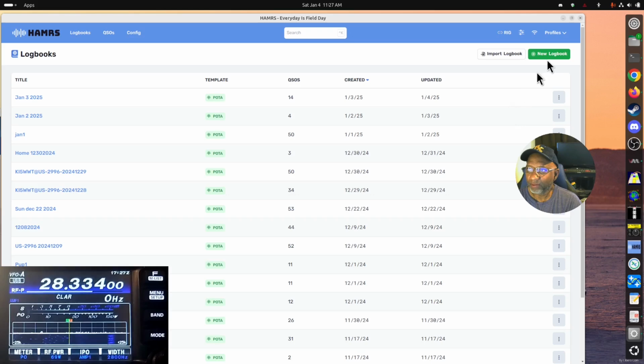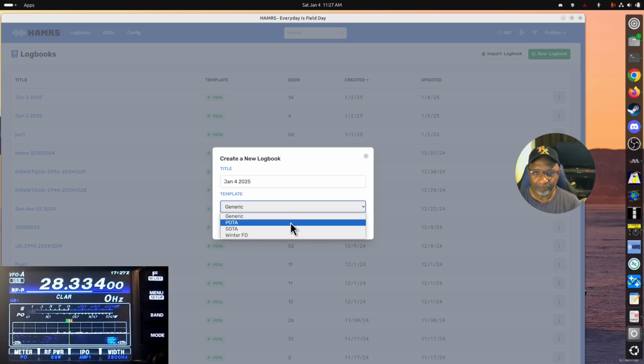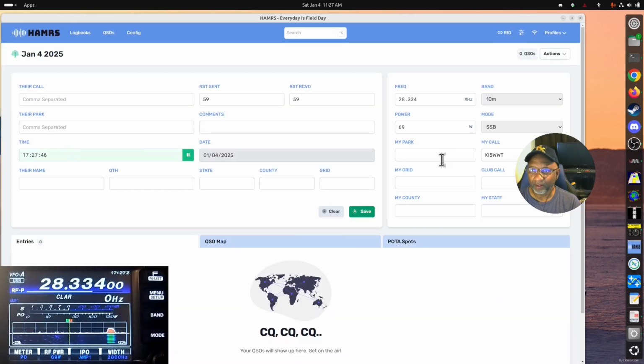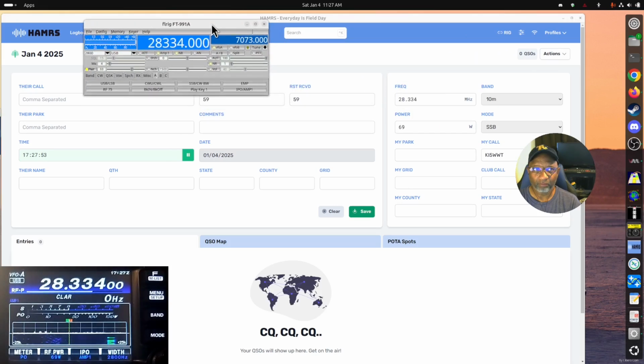So you go into Hamrs and you create a new logbook. You can give it whatever name you want. Let's call this January the 4th, 2025. And you select the template, which is POTA, Parks on the Air. You'll see that my radio is set to 28.344 and that the frequency here is 28.344, and it automatically puts in the band and the mode.